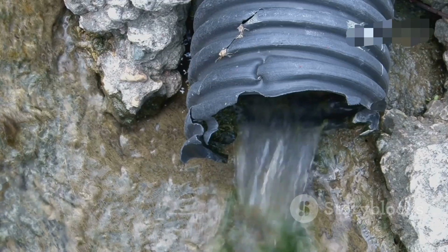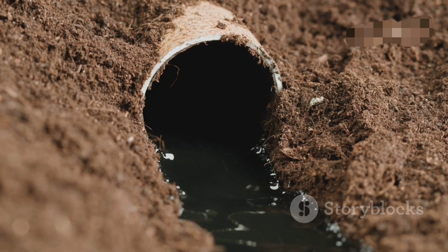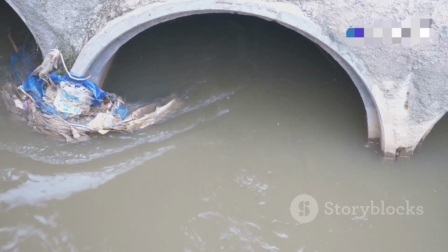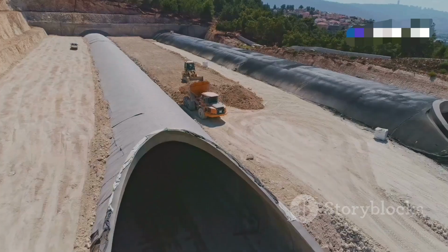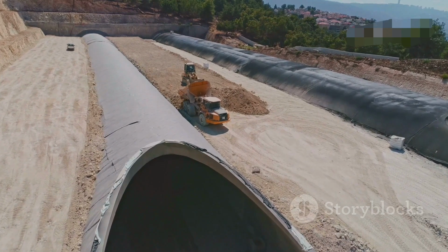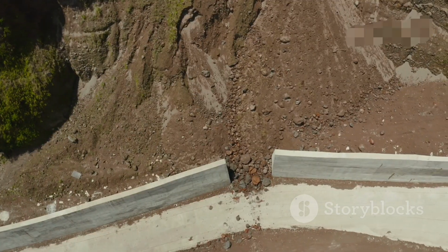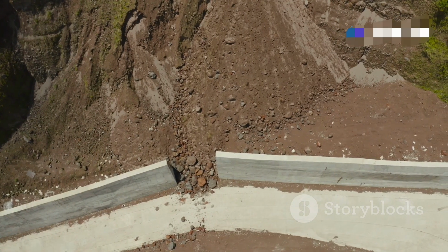In the case of earthen dams, piping is a frequent cause of failure. This process often starts with a small amount of seepage. If the seepage carries soil particles, it can gradually create a small pipe or conduit through the dam embankment. As this pipe enlarges, the flow of water increases, leading to more erosion. Eventually, the roof of the pipe can collapse, leading to a rapid and often catastrophic breach.